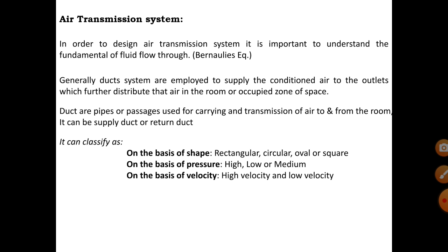Whenever you are designing any duct, there are a few things you should note down. The first one is the space which is available with you. You can't directly choose any particular shape as per your choice. You need to deal with the space availability: the space available in the building, the passages which are available, which we can employ there, the pipes which we can install there. You need to observe the space available. Along with the space, the second thing that you should know is about the noise level.